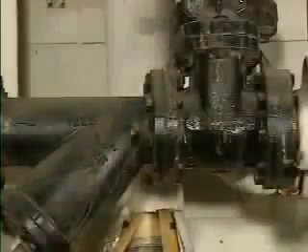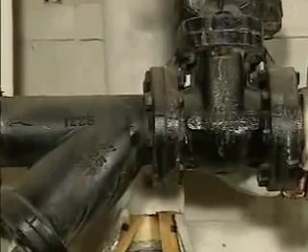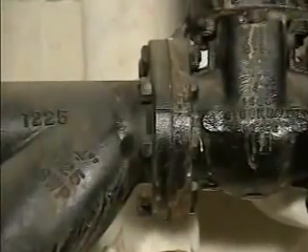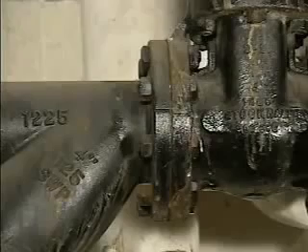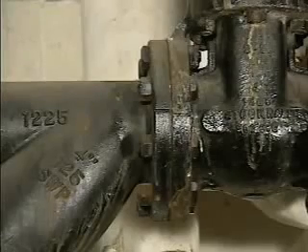For this reason, it is often used in high pressure and high temperature systems, such as hydraulic systems that push and lift heavy loads. Another characteristic of carbon steel is that it's less brittle than other materials, such as stainless steel, so it's able to absorb vibrations. Therefore, it is well suited for systems that generate significant vibrations, such as in vibrators used to make anodes and aluminum manufacturing processes, lifts, and large gearboxes attached to motors or turbines. Because it is susceptible to corrosion, carbon steel is generally used with non-corrosive gases and liquids.